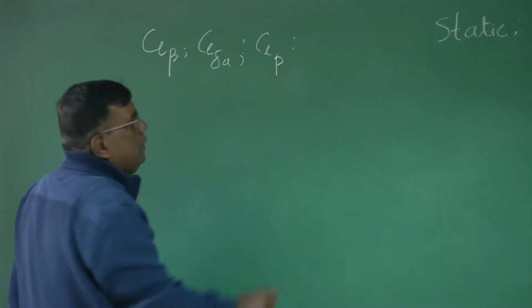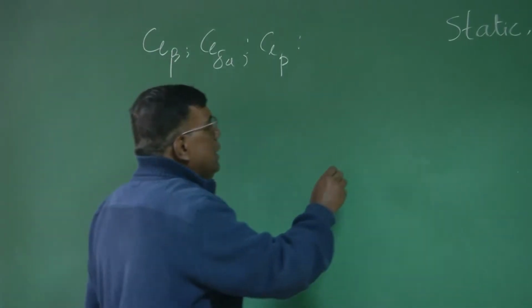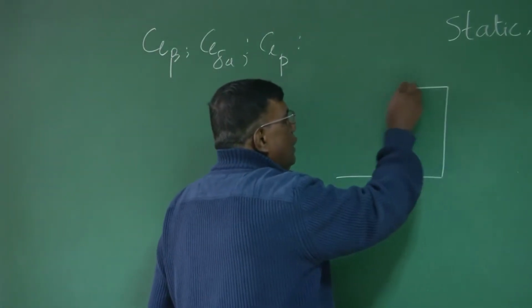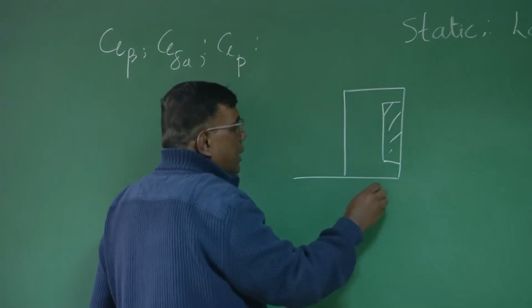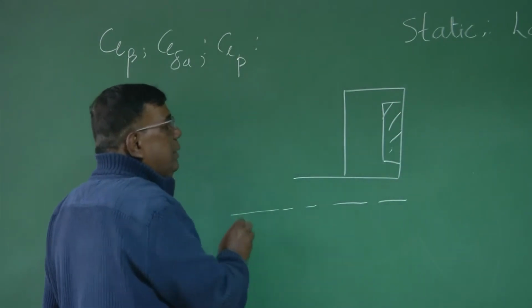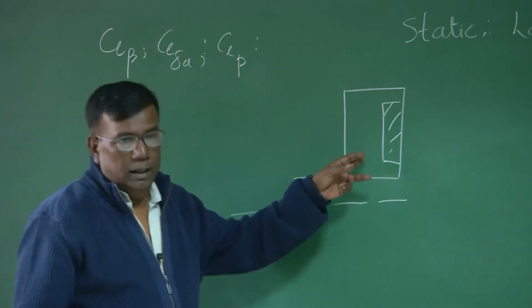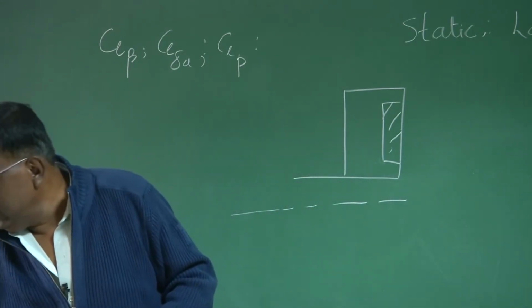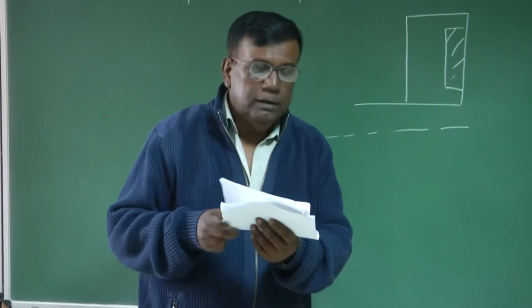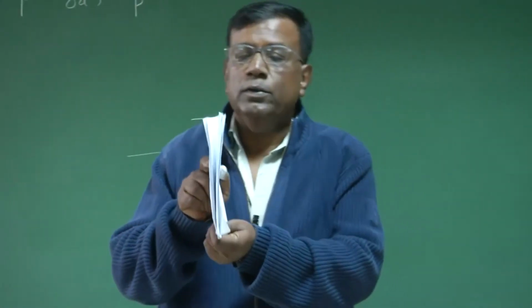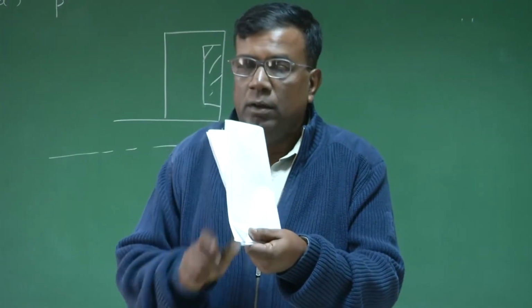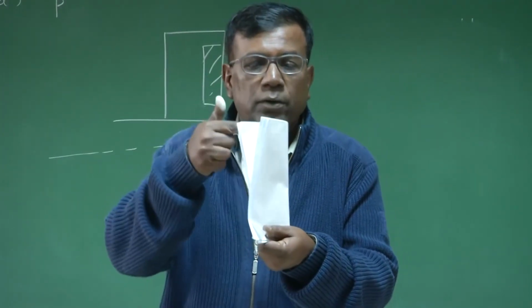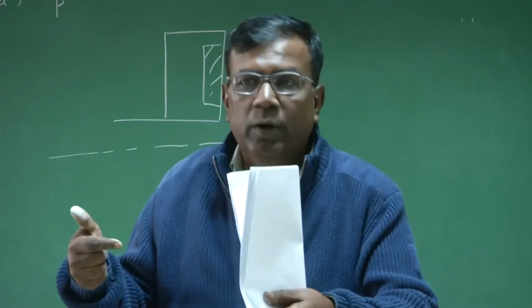Also, before I come to directional, you should also understand that if this is the rudder here, and let's say this is the center line of the airplane. Suppose this is the rudder over the fuselage. If I deflect it like this, it will generate a force in this direction, because it is moving in the forward direction.